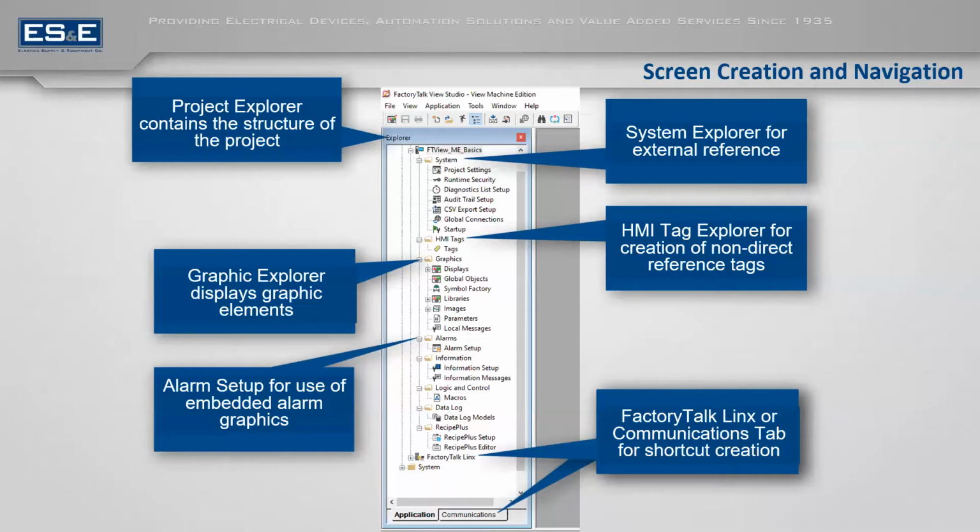And the last and potentially one of the most important tabs is your communications. So you have two different places where you can access it. You could either open up FactoryTalk Links and double-click communications, or you can just select the communications tab. But that is where you will create what they would call a topic, but it is giving the PLC a name and a path for the panel view to communicate to it. We'll cover that in a lot more detail when we get into our actual application.